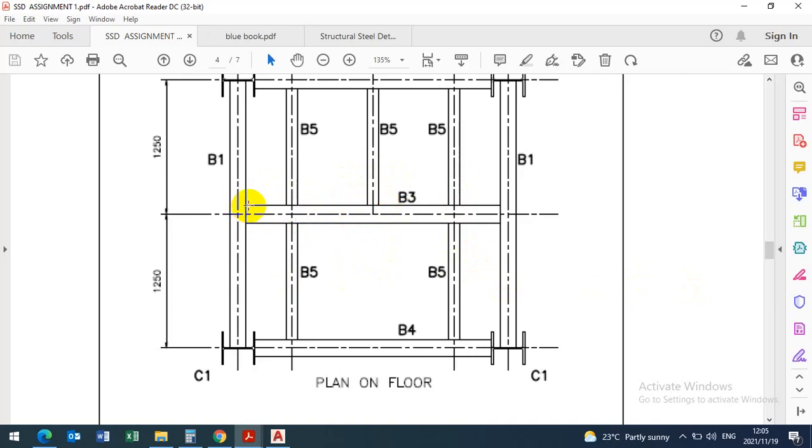Here you will do notching and then you will show the end plate detail for beam 3. But for beam 1, we are not going to show the end plate detail. We show only the position of the holes and the end plate shown here and there. Now we come to beam 3 detailing. It will have the end plate detail here and here, and only the hole position for this beam coming into this beam, just the hole position.